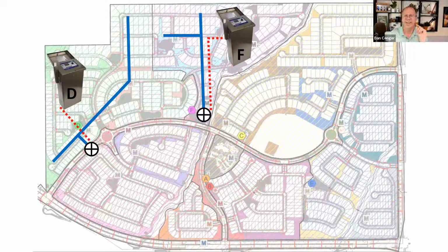Now, here, this kind of stuff happens, and this is what actually got installed. What happened was the wire path for the master valve on controller D wasn't connected to controller D. It was actually connected to controller F. Now, how does this kind of stuff happen? Well, it's pretty complex, right? You've got 1,000 zones, and I've been a contractor, and crap happens. And this is definitely crap. This is not pretty. So let's take a minute and unpack that.